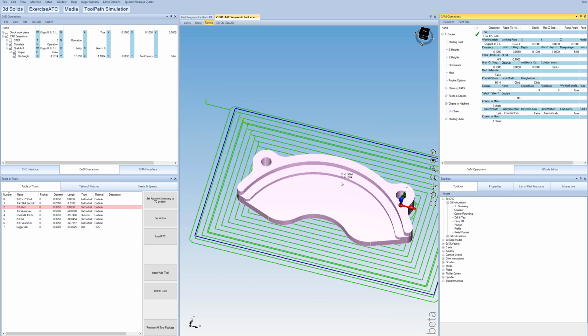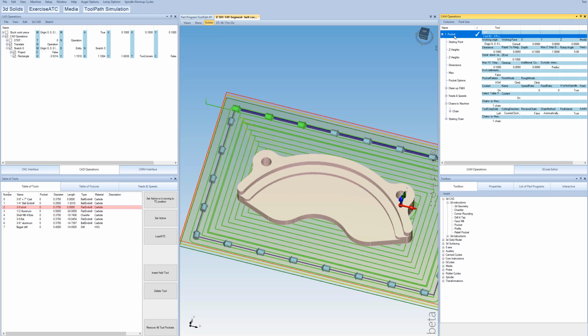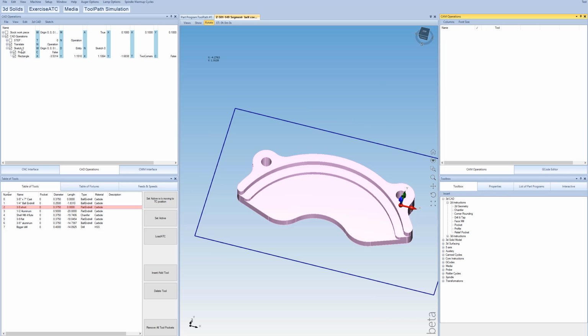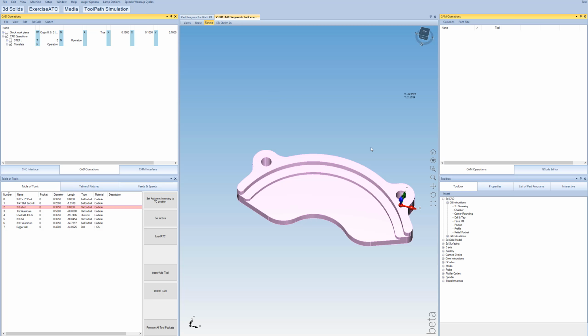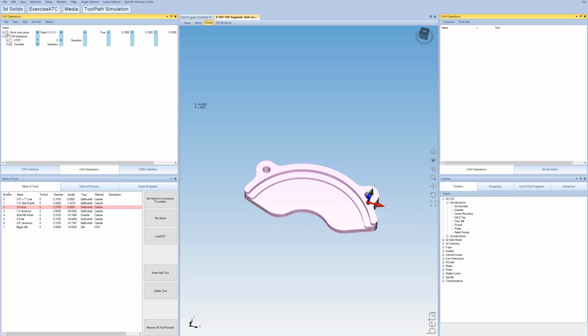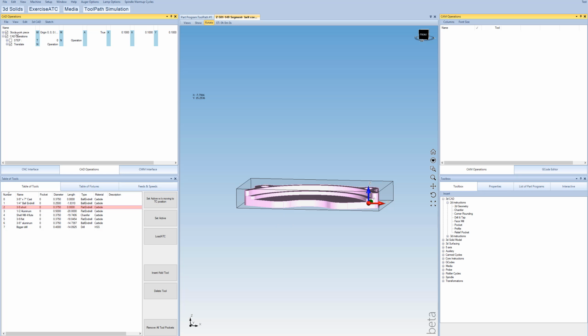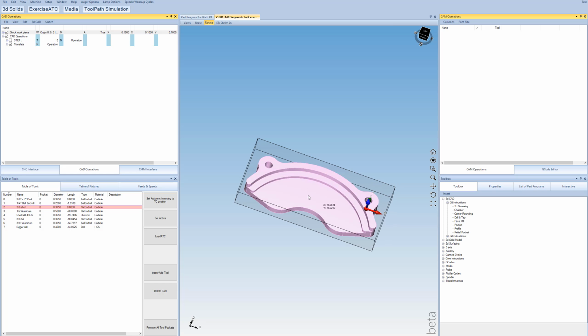Okay, so once we're done with that, let's go ahead and erase our fixture part of this program. We're not going to use it at all anymore. Once we made the fixture, we can pretty much just throw this out. So we'll erase the sketch and erase our toolpath. The first operation, this is assuming this is going to be our starting workpiece. You'd have to modify your starting workpiece, which I showed in a different video, based on whatever size of the starting material that you start with.